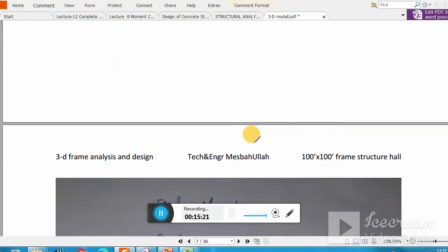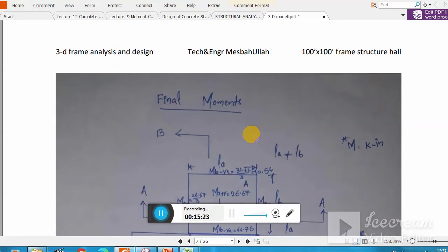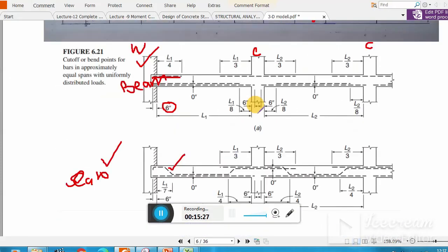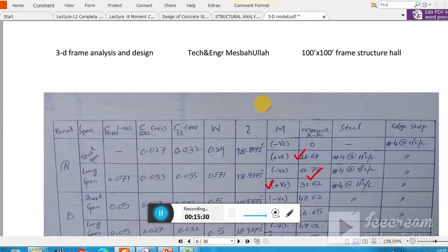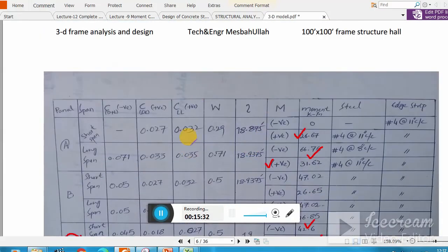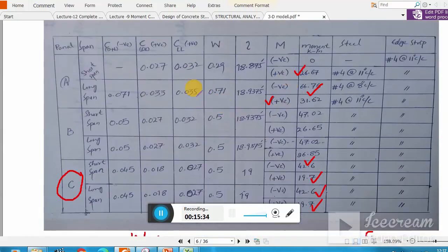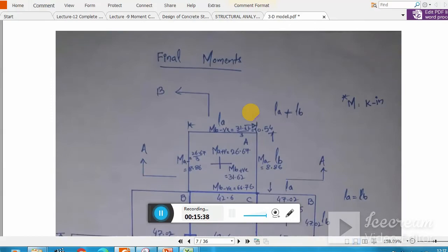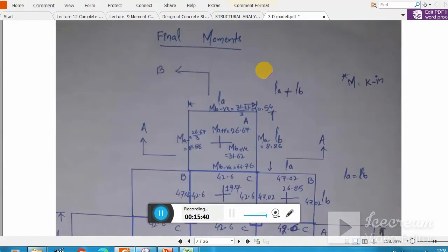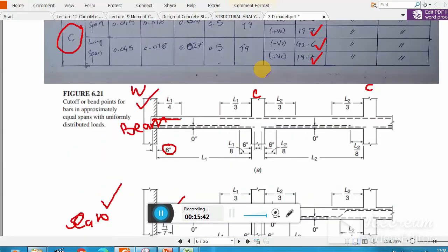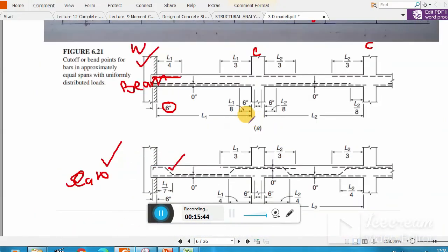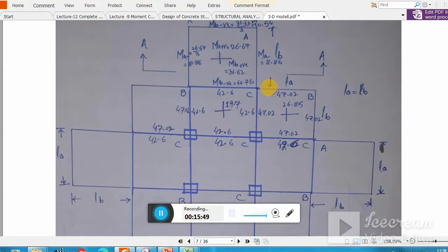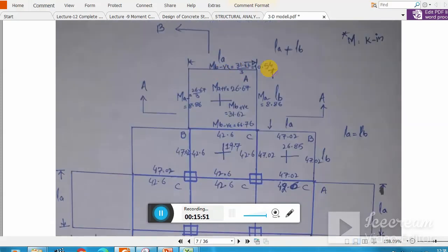In the next lecture inshallah you will see. Please understand these two tables, because the whole detailing of the slab system will be based upon this table. Let me finish this table as well. Once you get your moments like you see here, you need to represent those moments in this table form on the drawing, because this is easy.